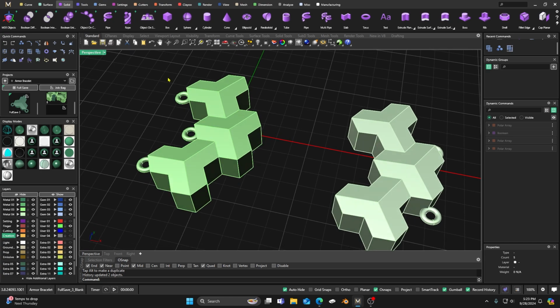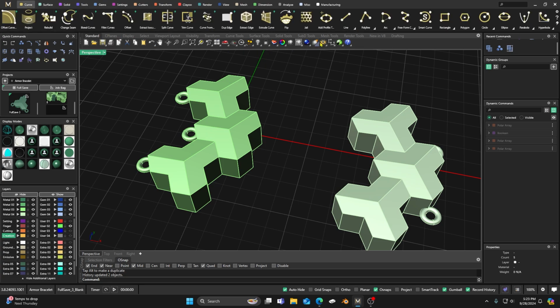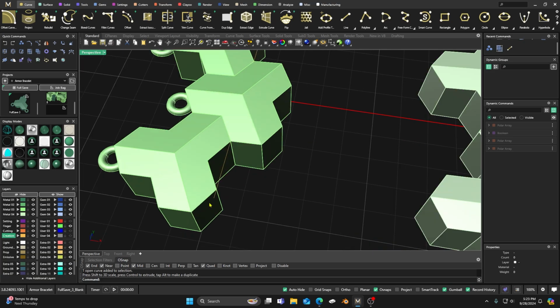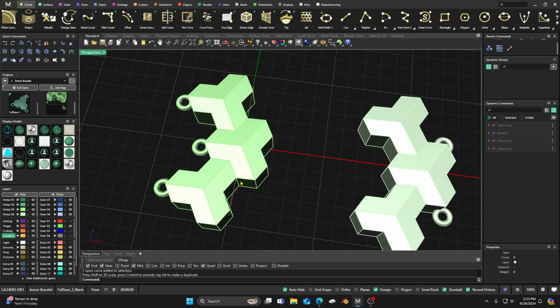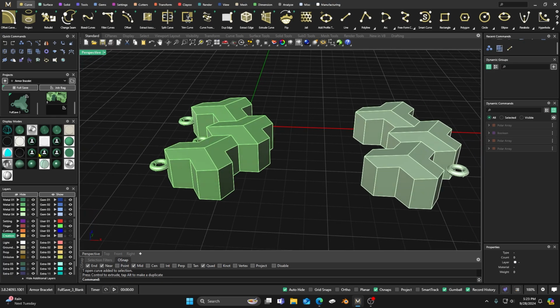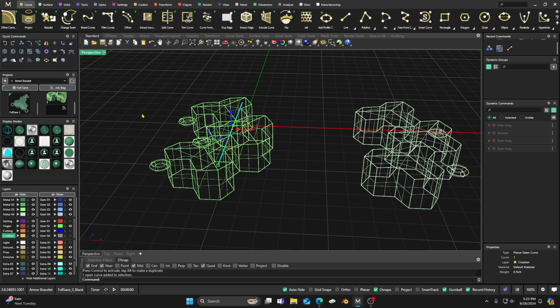So this is kind of, you know, we'll just go ahead and we'll just make a line. We got it at yellow, so we'll snap it to this edge here to this edge here, and then what I'm going to do is I'm just going to grab it and I'm just going to drag it out just a little bit more so it just comes out a little bit past this edge, right? Okay, but we need it back to here, so we're going to grab that curve again, and it doesn't matter really on this side how far you bring it back. All right, so we'll take it back there, but it will matter